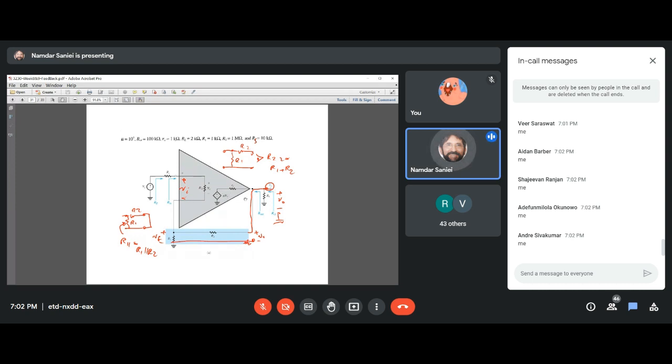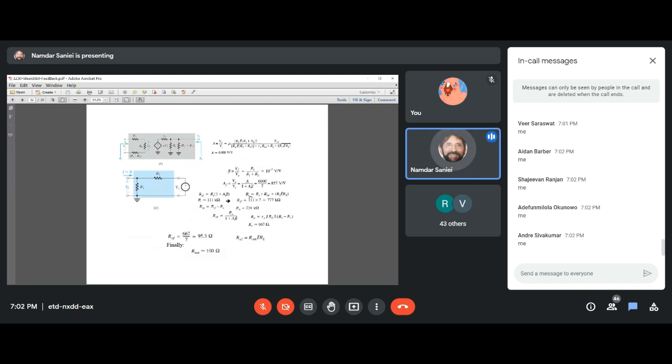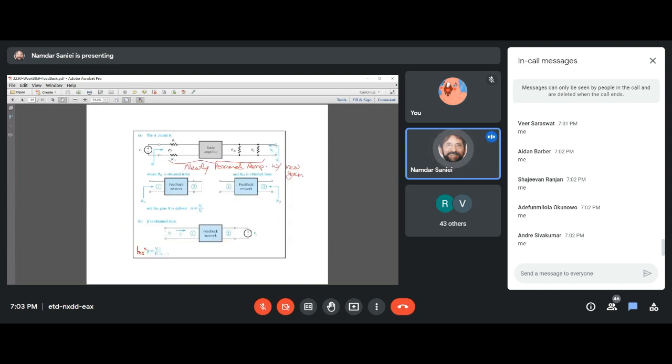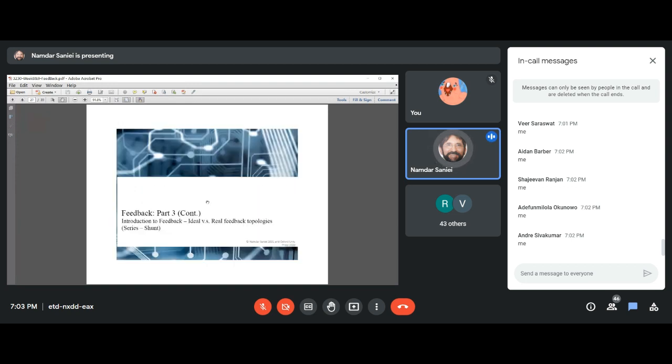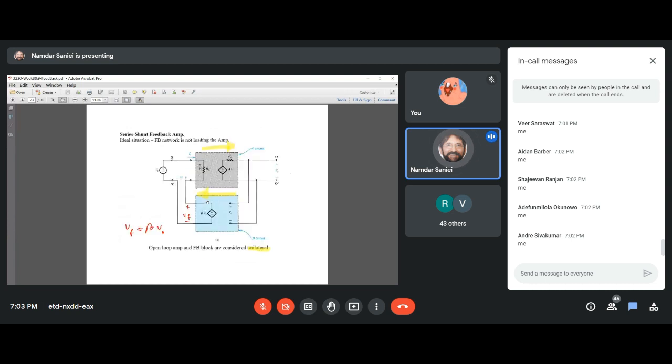Because the newly formed amplifier, that's what we called it, included RL. Why did we include it in the newly formed amplifier? It was because we wanted to make the feedback network and the entire circuit like the ideal form. Ideal situation was like this. No RL, right? So if we had absorbed RL into the amplifier, and if there was an RF also in the amplifier, our findings from this analysis would be valid, right?